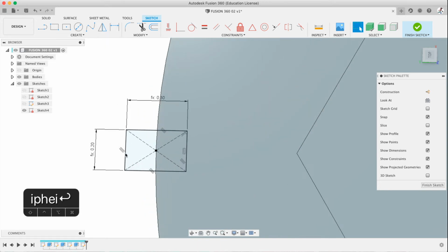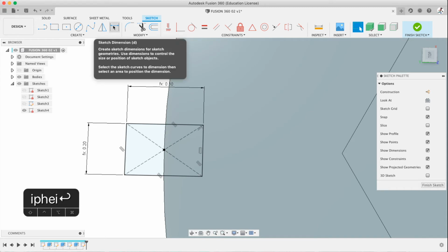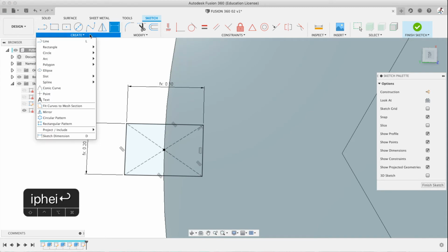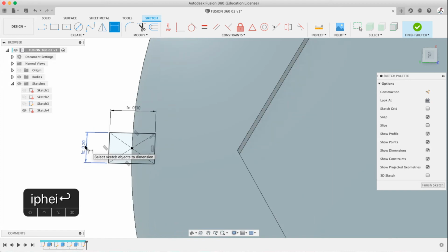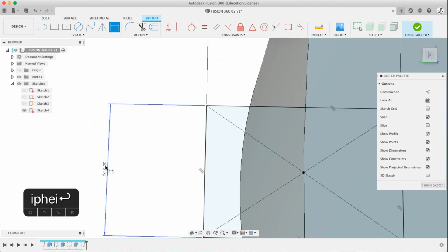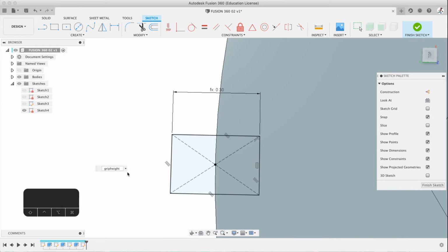This is sort of a next video, but I'm going to give you a quick hint right now. Sketch dimension, drop down sketch dimension. Where is it? At the very bottom, D is the shortcut. You can actually hit that and find that. It should highlight blue. If I go even further, it should be a bit more clear. Double click and you can change it. Hit escape to cancel. Right? Grip height, and it will change. What do we have? Grip width and grip height.